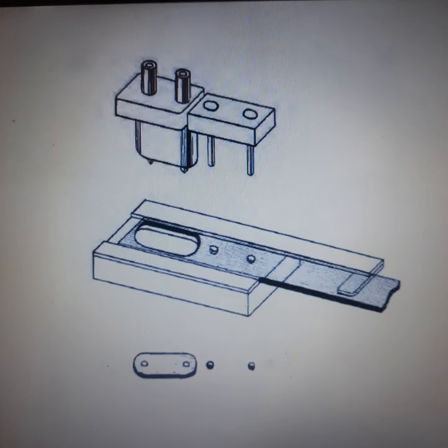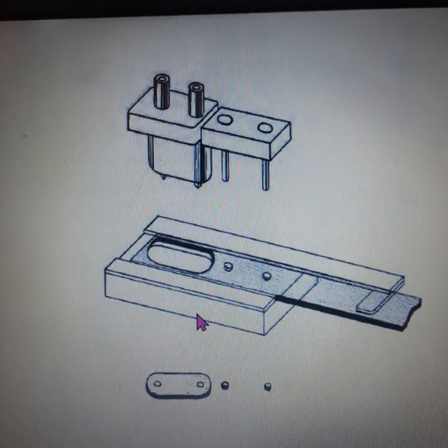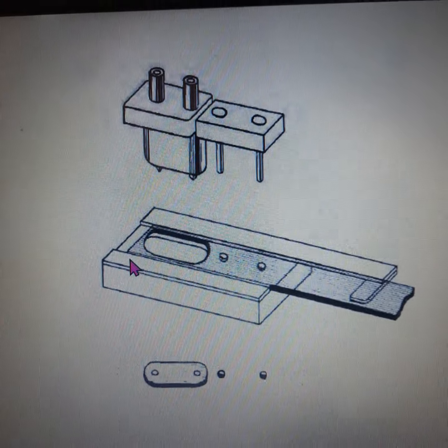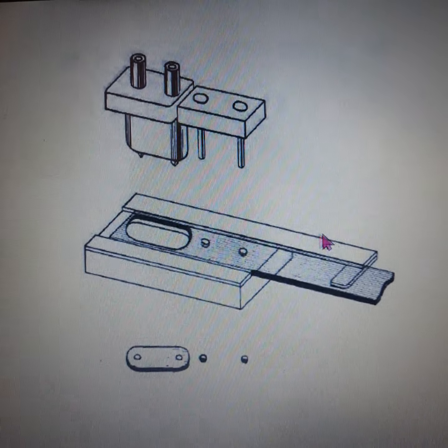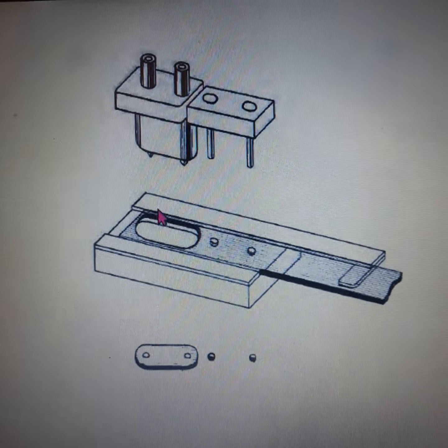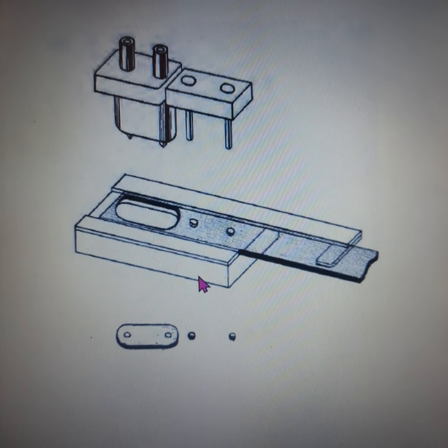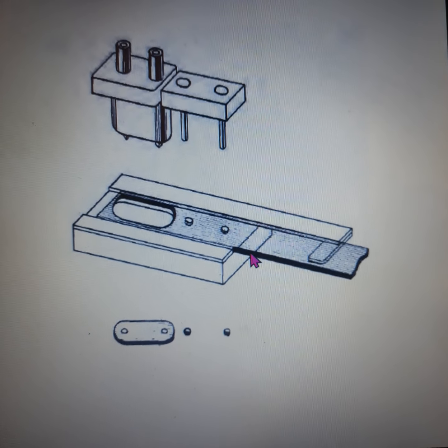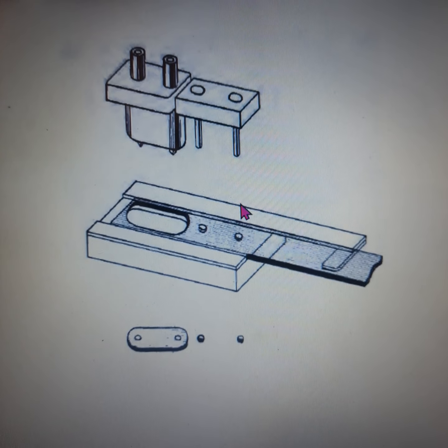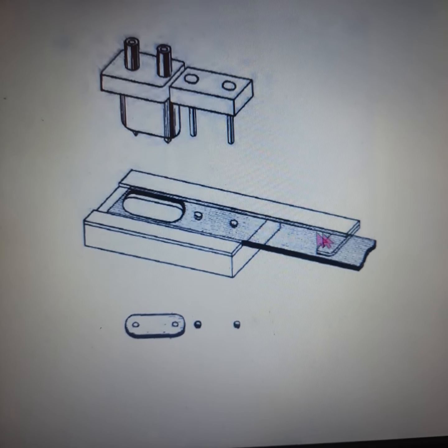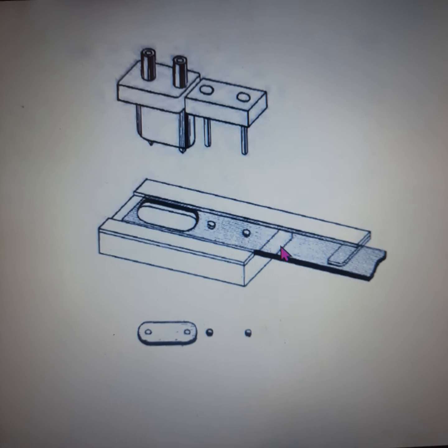So this figure shows the die plate. Over the die plate, a front cage is placed, and the back side a back cage is placed, and the back cage is longer than the length of the die plate because it has to support the feed strip. So when you place front cage and back cage over the die plate, a channel is created, and this channel is used to feed the feed strip.